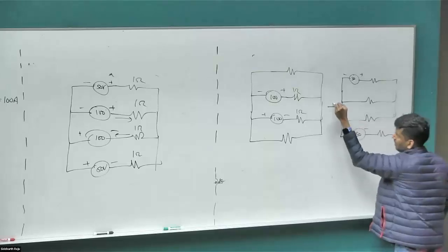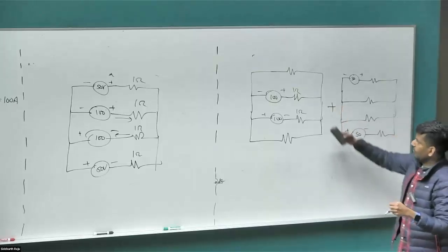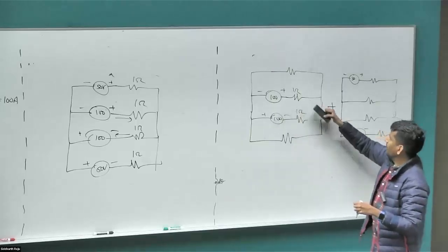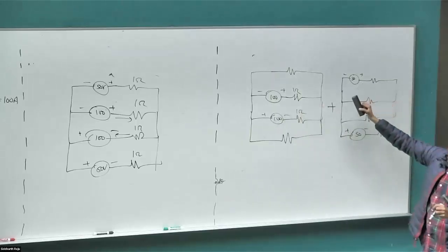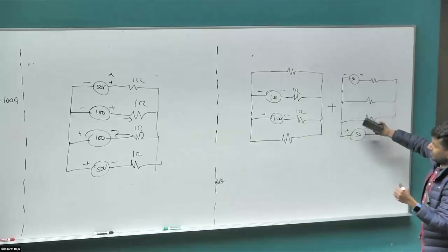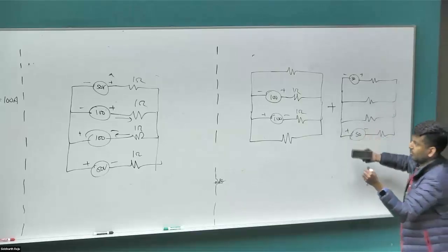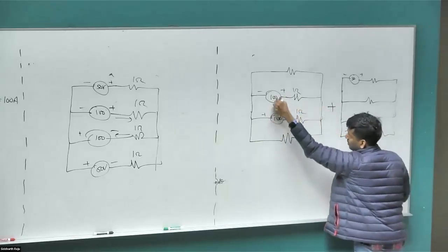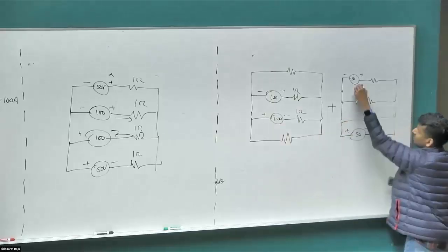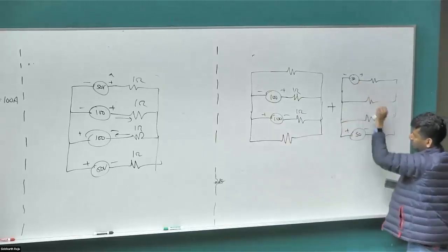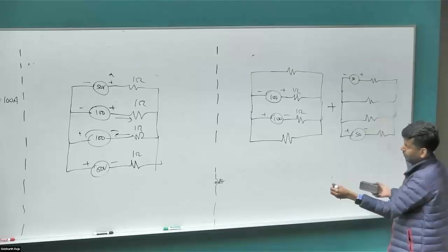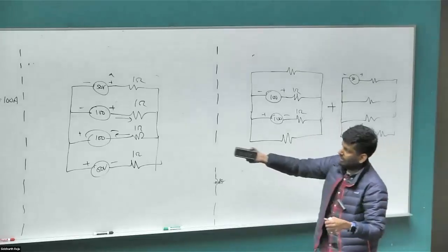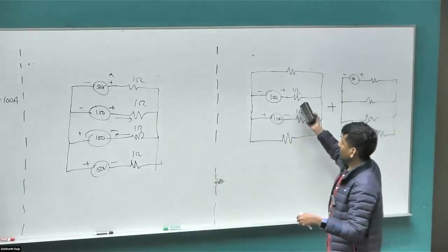Right? If I want to figure out the current through this network, it will be due to the currents of this source plus whatever the current of this source comes out to be. Again, I could have broken it down the way superposition would like you to do: have this voltage source alone, this also shorted, and then this voltage source alone, this also shorted. That will give me 2 circuits. Net of 4 networks. Sum them up together and we'll get the results. But this is much easier because I already figured out the case where I just had 2 power supplies, what the currents are going to be.